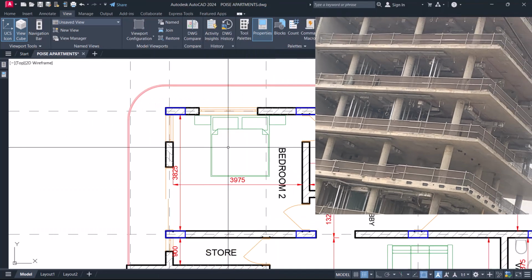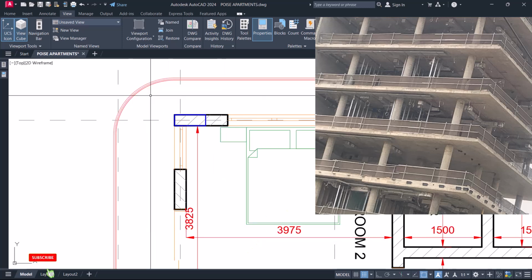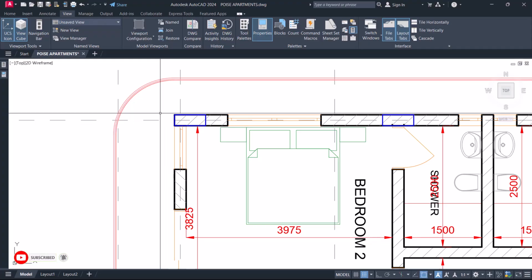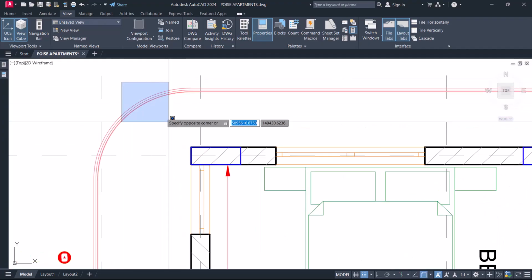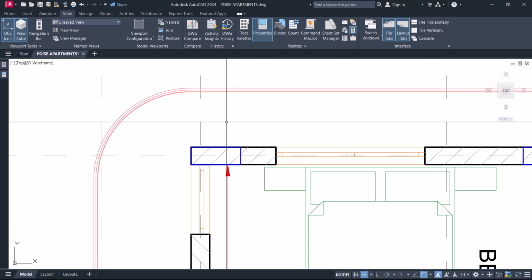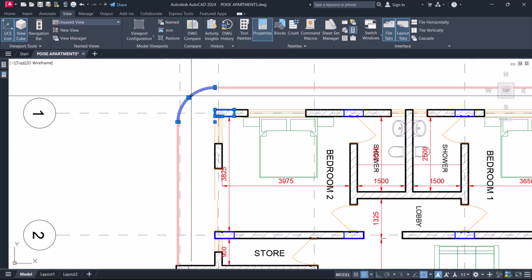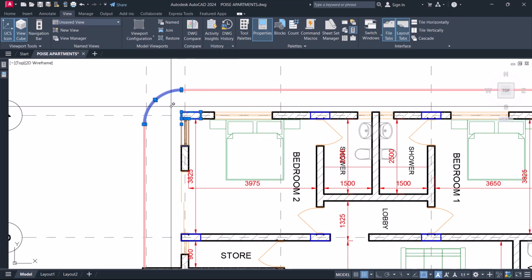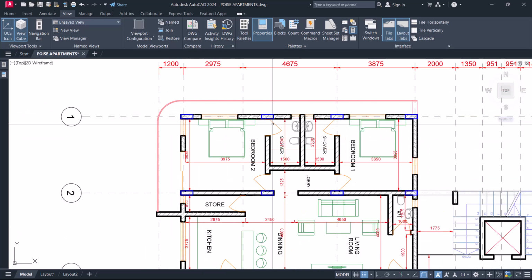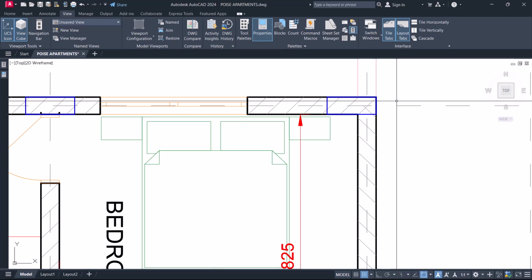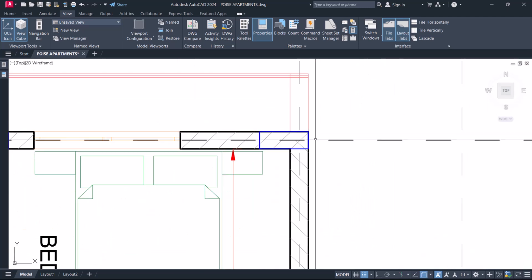So what we'll be doing in these cases is picking out these slab panels, and due to the moment transfer principles of our flat slab, it is very advantageous to have slabs surrounding our columns, just like we have here. We have a curve over here surrounding this edge of this column, rather than having our columns at the edge of our structure.